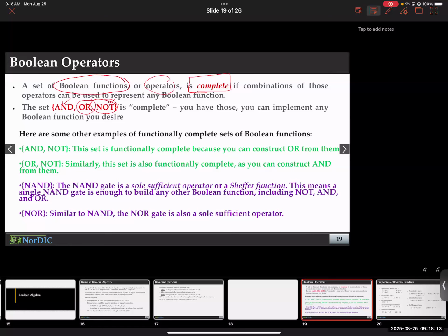But there are other logic gates like NAND, for example. NAND is nothing but, say, not AND. Just take AND and invert the output. That's all. Flip the outputs. That's what NAND is. Okay, we'll take a look at the truth table as well very soon. But just keep that in mind. It's similar to AND, except for the fact that you also invert it.